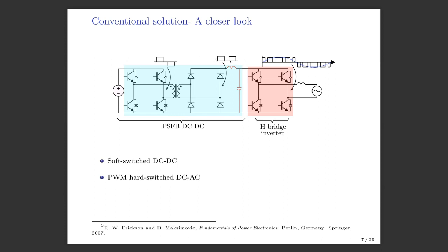So only the average of this waveform will appear across this bus, which will be used to invert here by this inverter. Now this is very much like your buck converter. This is essentially the principle of a buck converter, right?